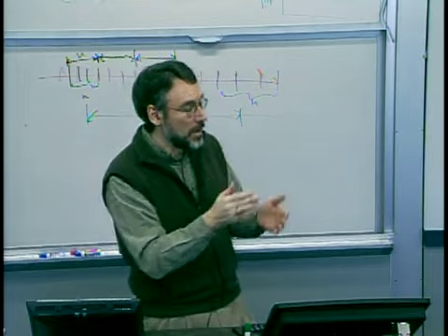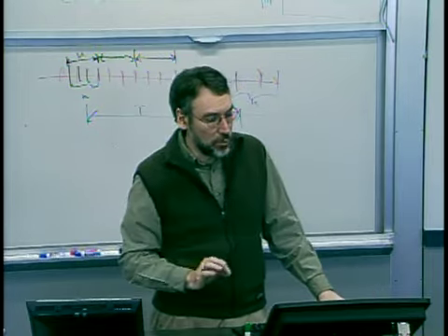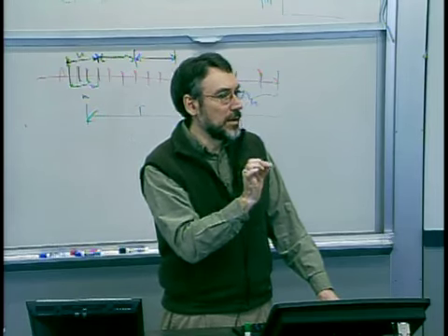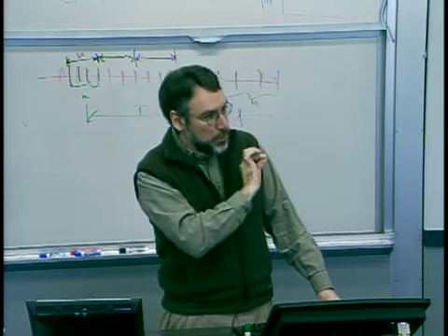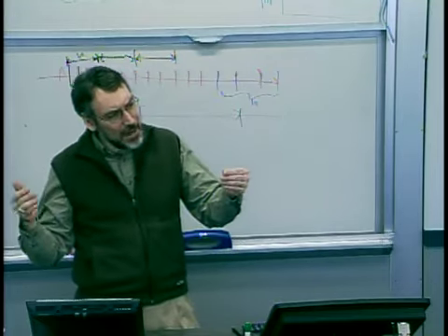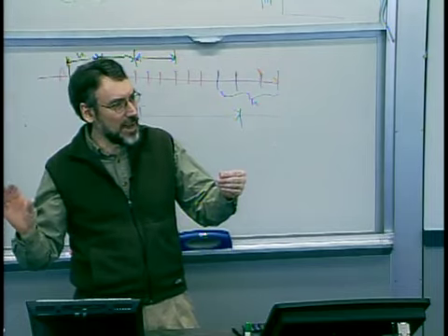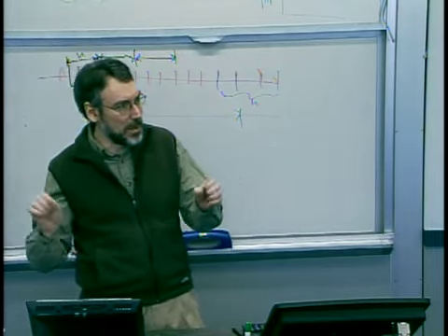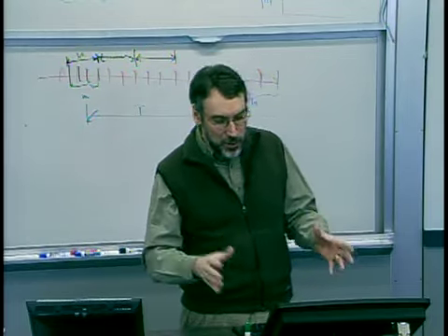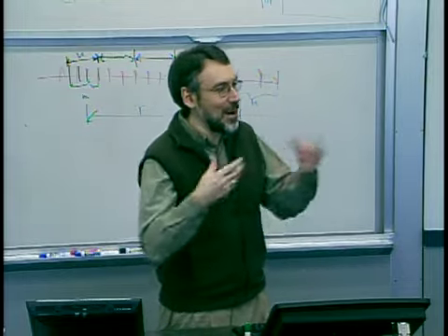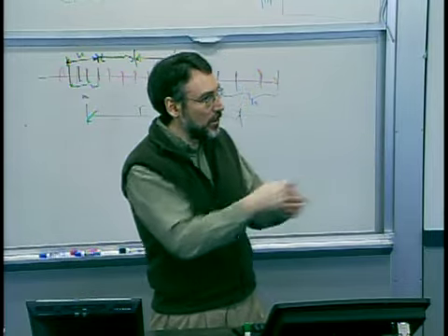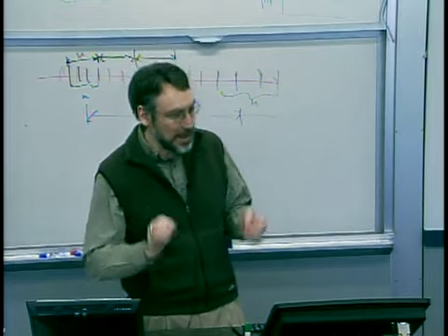It's okay if they both deviate together. And so what I would do is, if the importance is the difference between those two dimensions, that's what I would characterize, and that's what I would chart, put a plot on, and that's what I would set my spec limits on. I might also still care about, say, channel length, and so I might have another chart on that too. I have to be careful because they're not completely independent. But what you really want to do is get your statistical process control apparatus targeted at or applied to the things that are most critical to you. And so in your scenario, the tracking between those two parameters, that's what I would monitor.